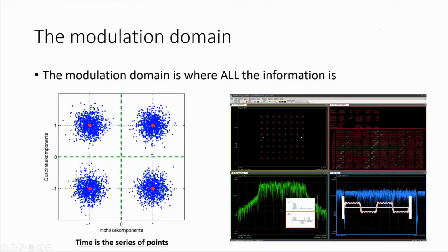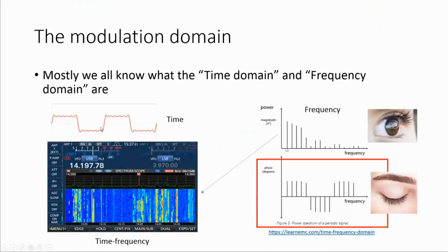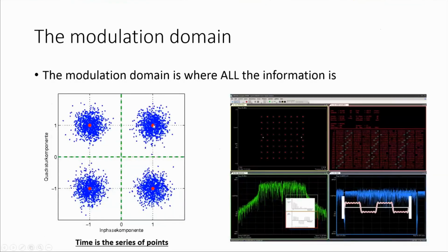So here's 4 states. This is QPSK, or it could also be offset QPSK. So you could either put it on the axis or off the axis. So there's 4 different modulation states. So here we're on and off, that's one state. We can be at some frequency, but here what we're saying is we're at a phase state and an amplitude state put together. So these exist simultaneously.